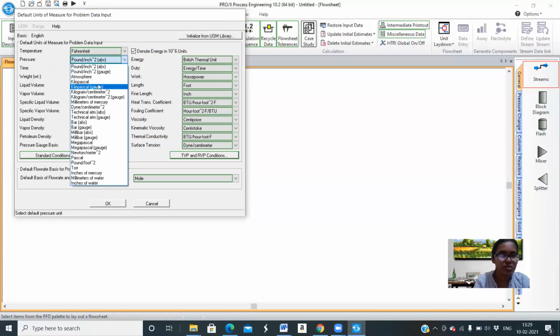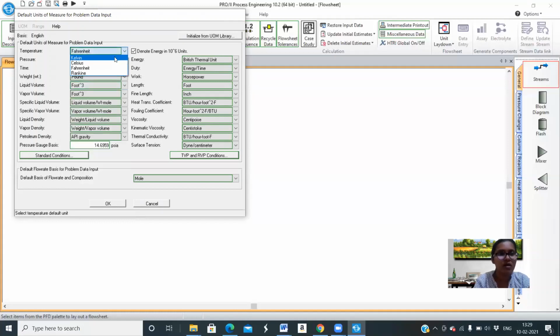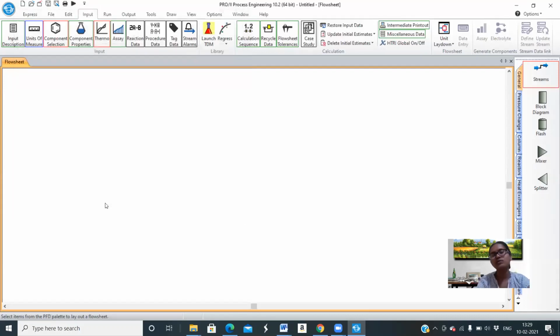We can change to anything. I'm changing the temperature to Celsius and pressure to kilopascals. And I'm changing the weight to kg. Okay. Now click on OK. If you don't click on OK, whatever changes you made will not be saved.